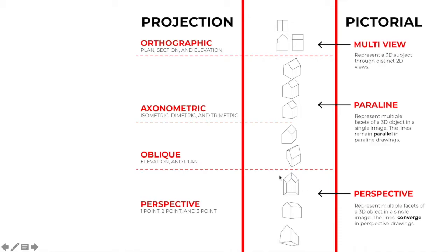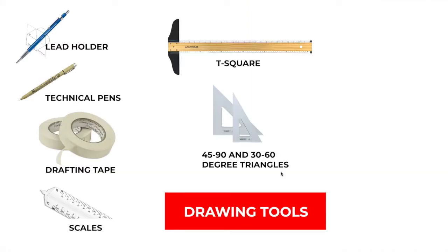And then perspective, we typically talk about 1 point, 2 point, and 3 point perspective drawings. 1 point has all of the edges that are parallel to each other and perpendicular to the picture plane vanishing to 1 point, edges that in a 2 point perspective vanishing to 2 points. And then if we're dealing with something either tall or elevated, or if we're looking down at it from the air, we will in fact experience 3 point perspective in the case of skyscrapers or even natural settings like a ravine or a canyon or something like that. We'll start to look at 3 point perspective to represent that.